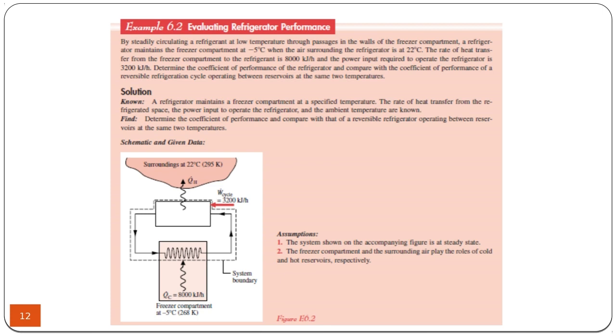Another example says that a refrigerator has a cooling capacity of 8,000 kilojoules per hour, and inside the refrigerator is given as -5 Celsius. You have to convert the temperatures to kelvins. So when you use the temperatures in efficiency calculations or capacity calculations, coefficient of performance calculations, you need to convert them to Kelvin by adding 273 to the Celsius. So you have to do this conversion before you start the calculation.